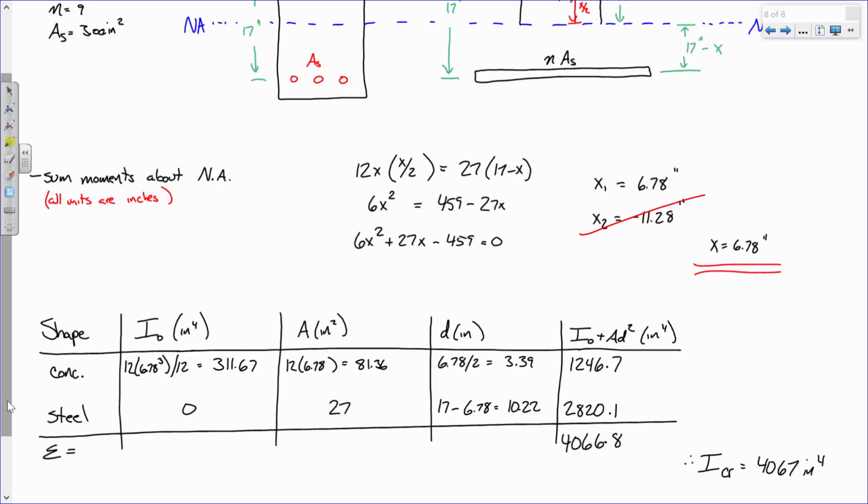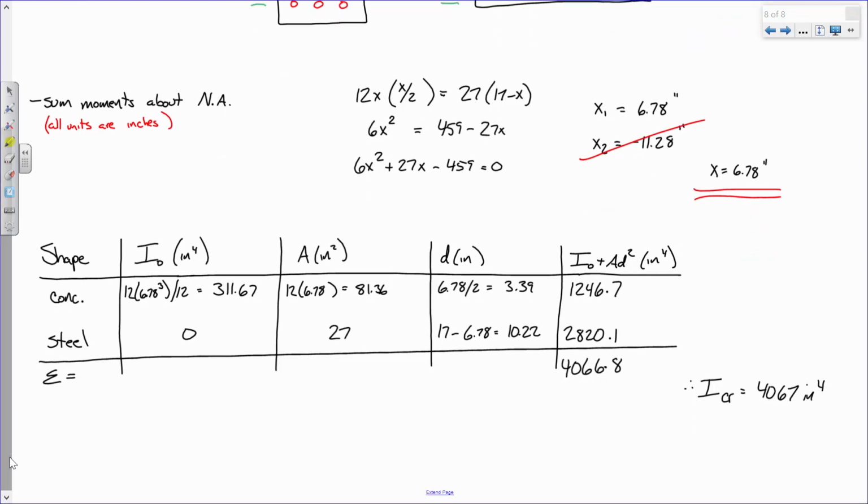Now, one thing I will go ahead and tell you later that we're going to look at, so this isn't going to matter now, but I'll just show you for later. So here's a beam with a distributed load, right? And so what's the moment diagram look like? Something like that? So if this is like 70, and your cracking moment is, let's say, 30, then your cracking moment is probably going to occur about right here and about right there. Does that make sense? So some of the beam is going to be cracked and some of it isn't.